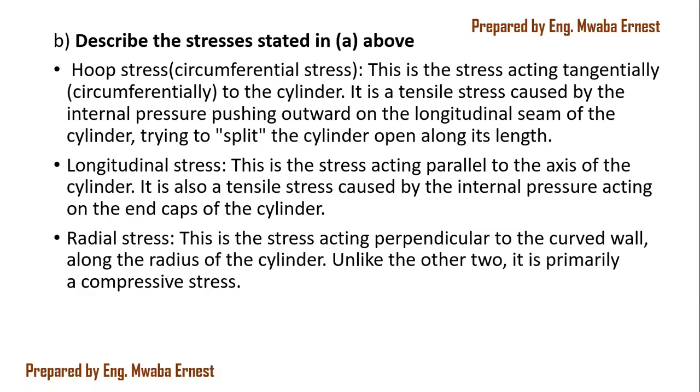This is the one I tried to talk about, that actually it's along the radius, meaning the stress normally acts perpendicular to the curved wall, or simply along that radius of the cylinder, so away from the other 2. Now this one, you notice that by nature, it's a compressive stress because it will try to compress the thickness of the cylinder as the pressure inside there acts outwards.